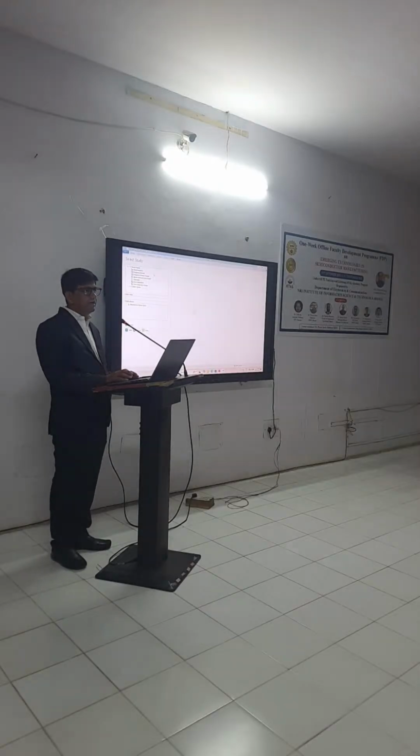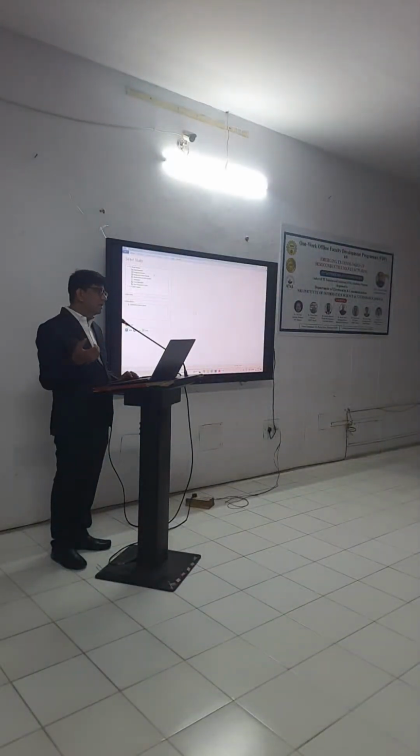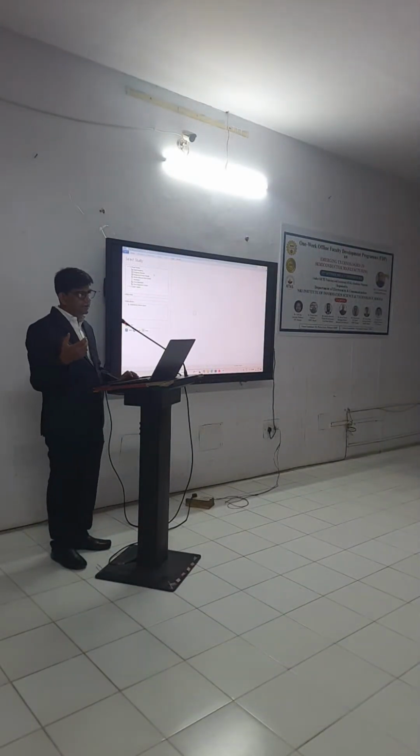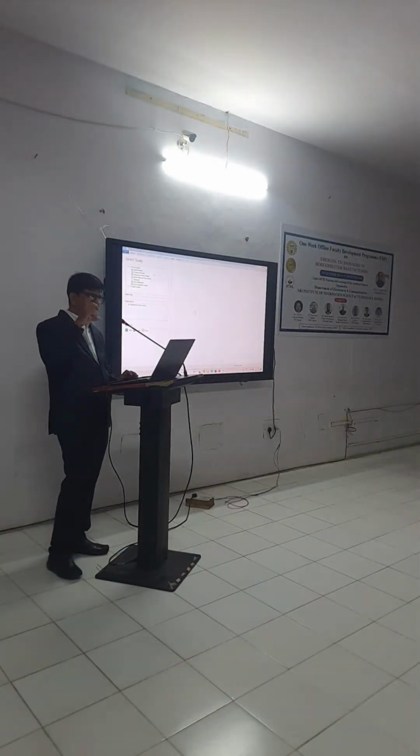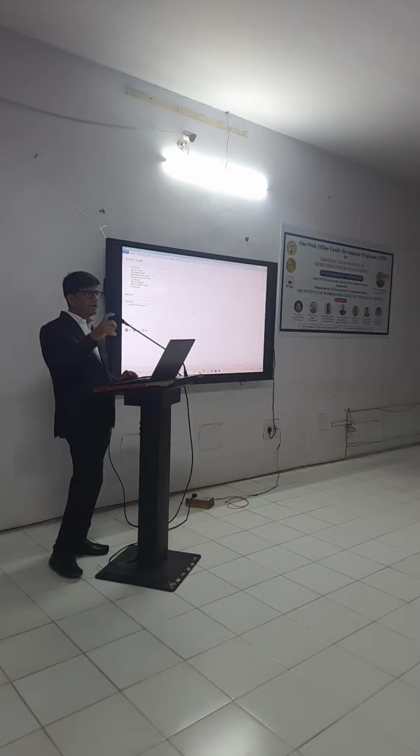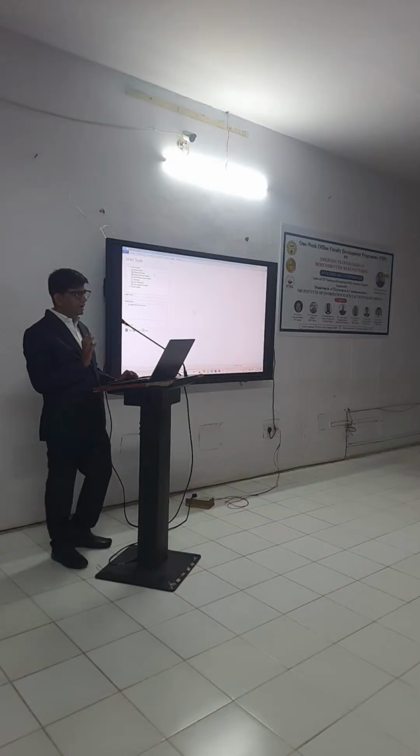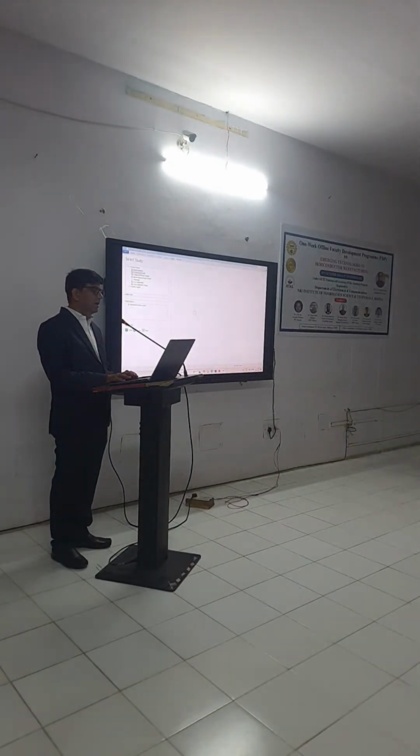And once you have an idea about device frequency, because here we do not need to find out the eigenfrequency, because we have an idea based on my acoustic velocity of the piezoelectric layer and the thickness of the piezoelectric layer, I can easily find out my resonant frequency. So I need not go for eigenfrequency analysis. So I will select frequency domain analysis as my study, and then done.